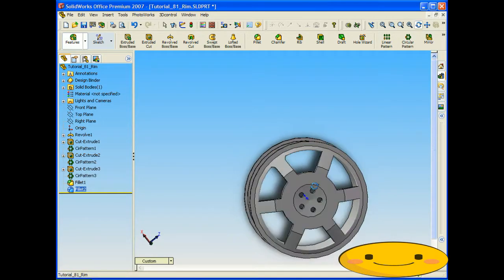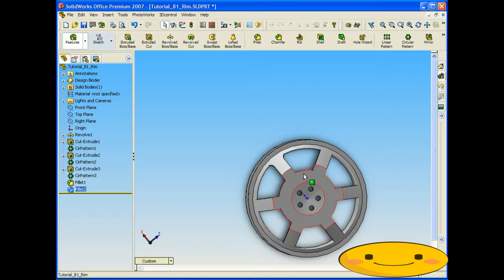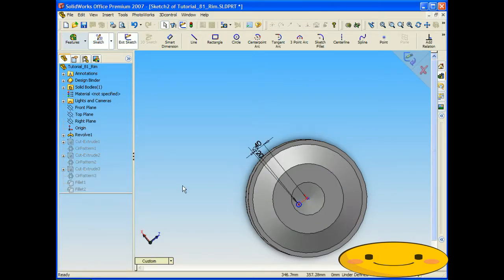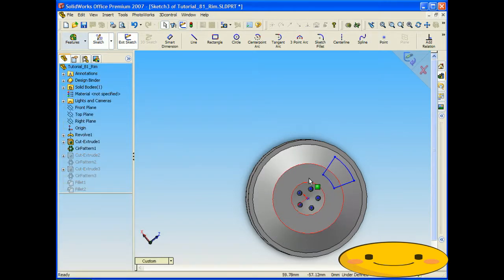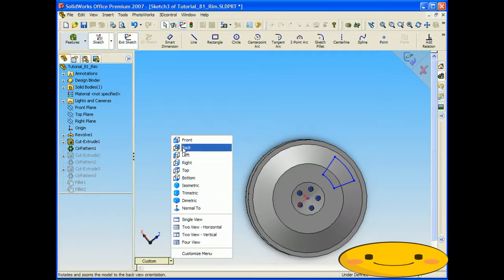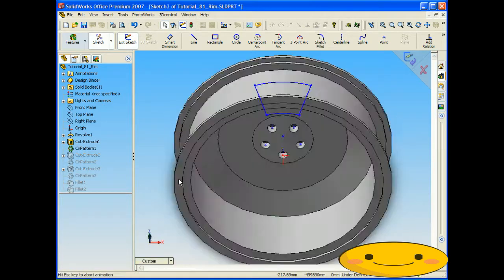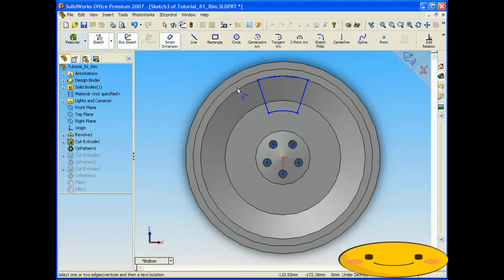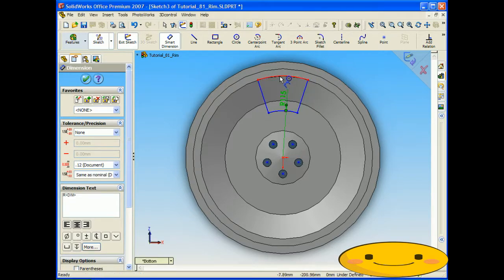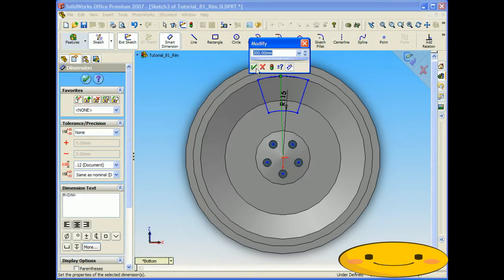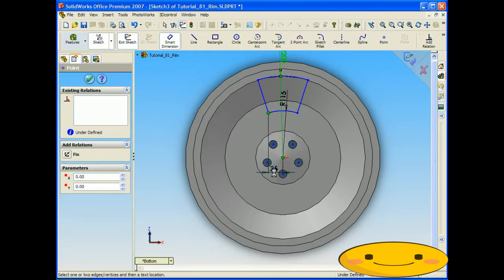If we want the center to go in, we can edit the sketch, and what we were using as our dimensions, we can pull it in. So let's try that. Let's click edit sketch. Wrong one. This one here. Edit sketch. And let's click the front view, bottom view, and let's throw a bunch of dimensions on there that we had before. And we need to put all these dimensions on so that we don't lose our positioning where everything was. So just throw all these around.